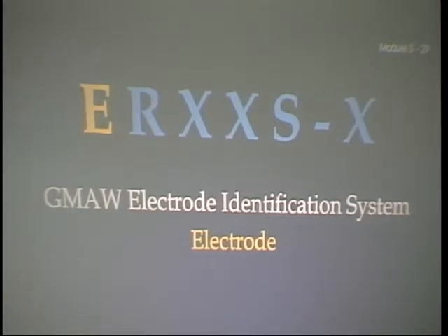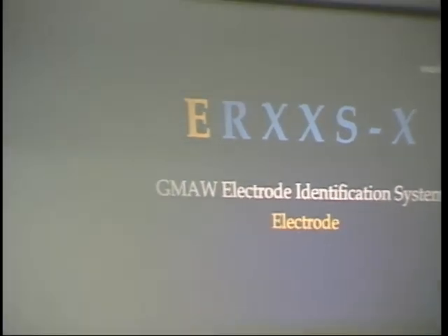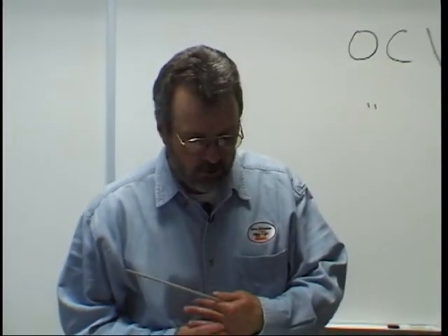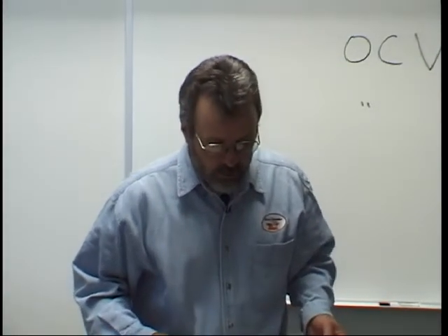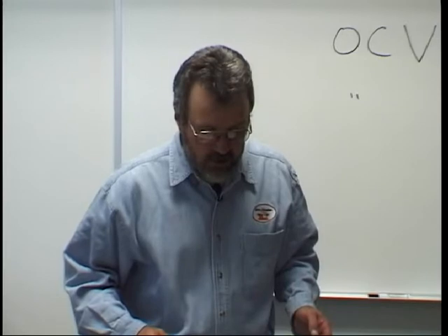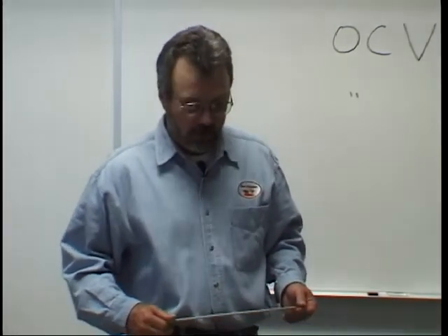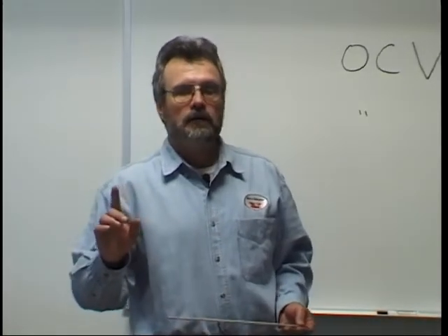Probably the most important one is that it's got to match the composition of the base metal. Then after that, you want to control various weld properties, to deoxidize the weld deposit, to promote arc stability and desirable metal transfer characteristics. And then wire composition usually matches that of the base metal being welded. That's a bullet. I think that's the number one reason.